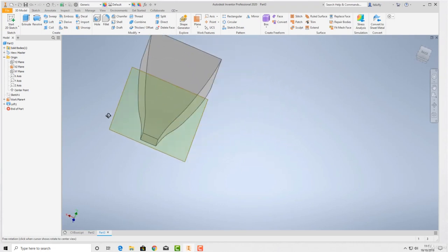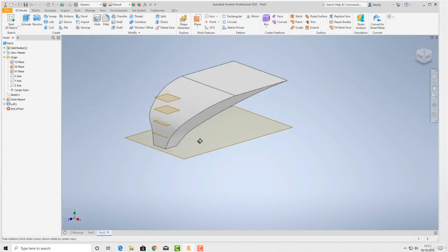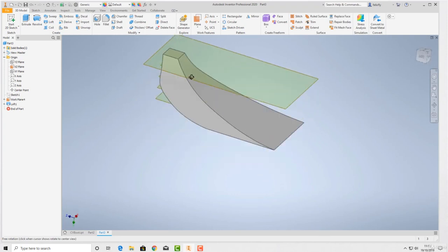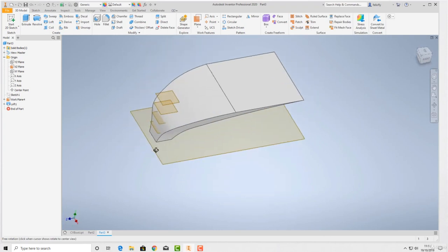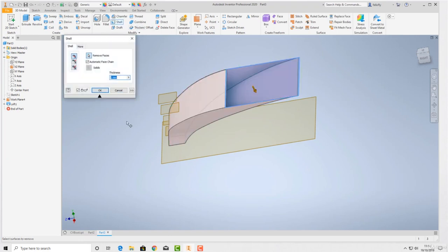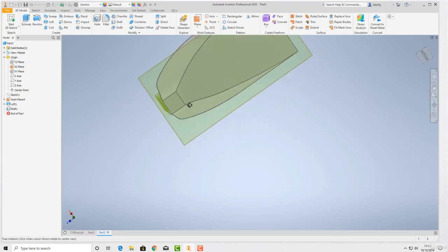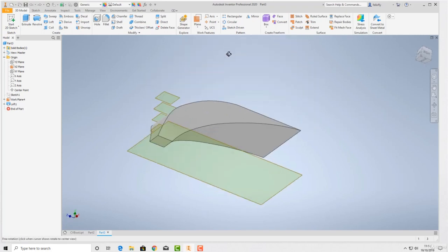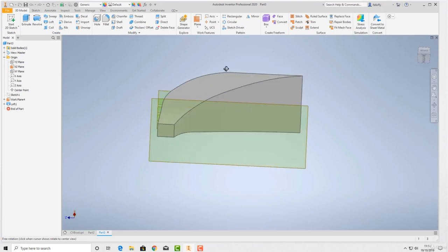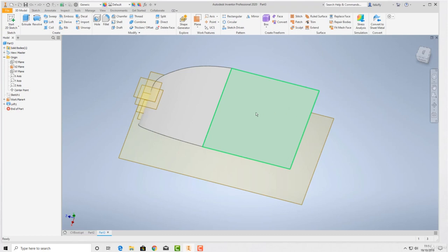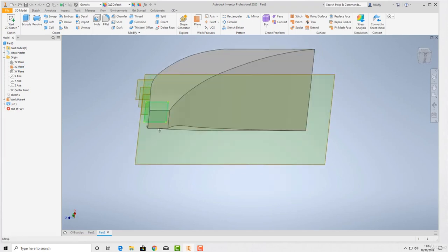So there you have the shape created from loft, and this would have been fairly complicated to model. Don't ask me what it is. It might look less strange if we shell it out. So when I shell this one out, I'm imagining that this is some kind of air duct with air going in here and being compressed down and coming out here.